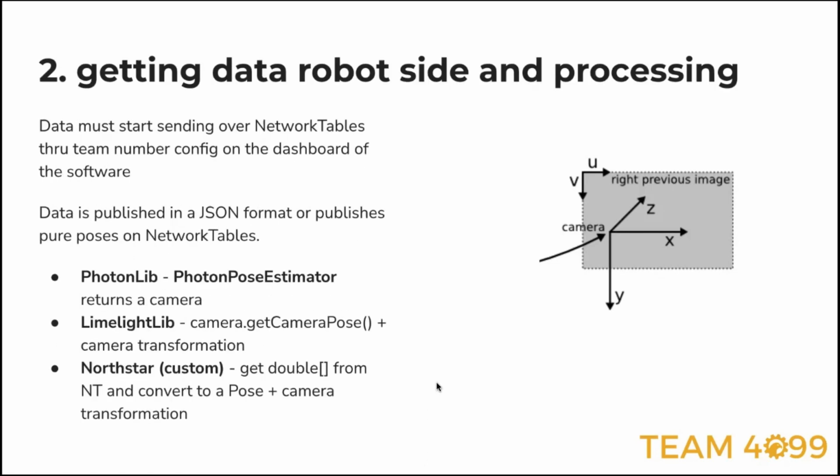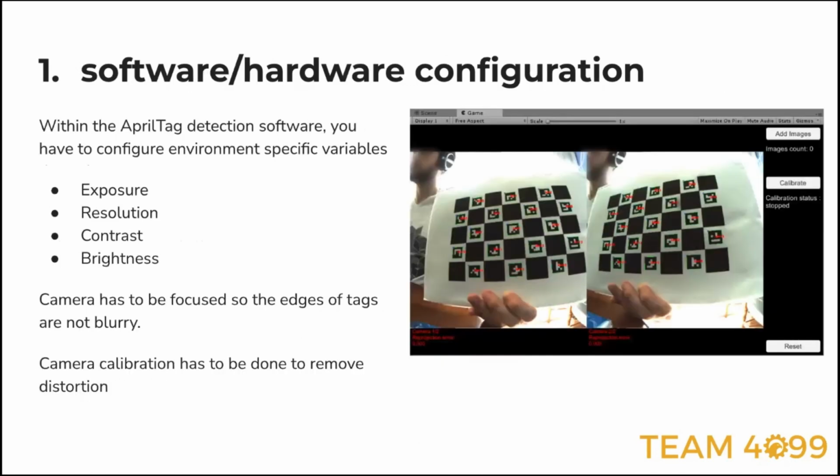And then if we want to go into more about how we do camera calibration, there's a bunch of different software that you can use. So OpenCV provides their own camera calibration tools. You can just take a bunch of photos of a ChArUco board, which is right here, and then it'll figure out your distortion matrix, as well as your camera intrinsics matrix. And then if you use something like MATLAB, you can just upload the photos, and it'll visualize your camera extrinsics as well as your camera intrinsics. And you can use this to throw away certain photos that are making your calibration worse.